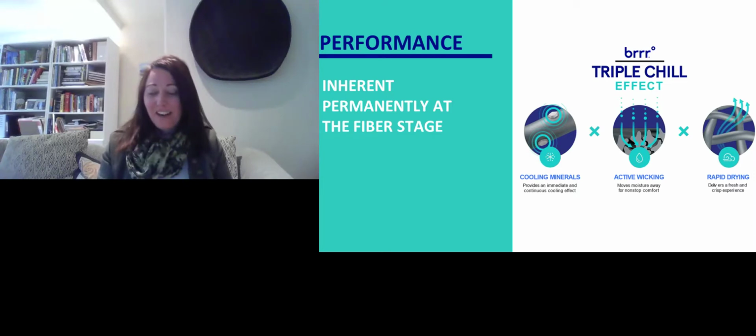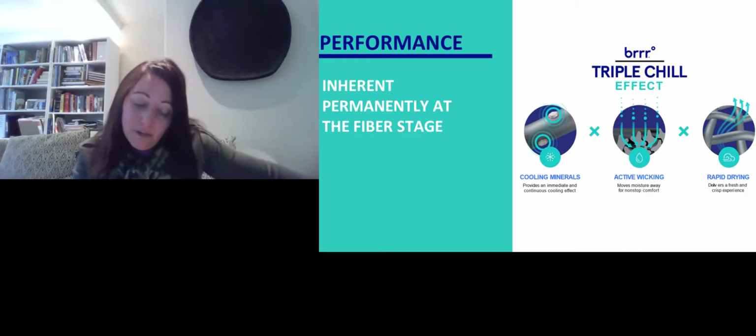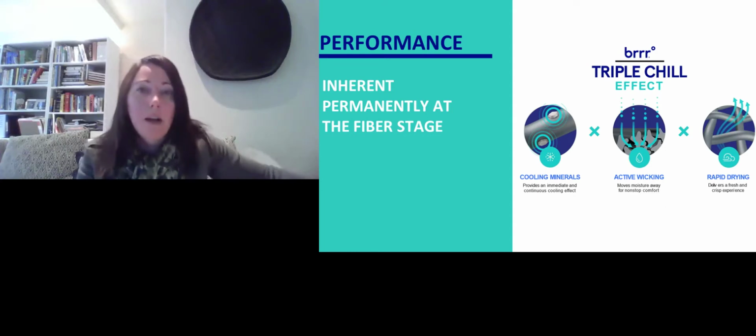The standard for active wicking we use is AATCC 197. And we set our standards higher than a lot of brands, or we test to meet the requirements of the brands. Our goal is to keep the wicking under 3 minutes, which is how much time it takes for the water to climb. The majority of our fabrics test at under 1 minute in wicking. So you want to have a fast wicking.